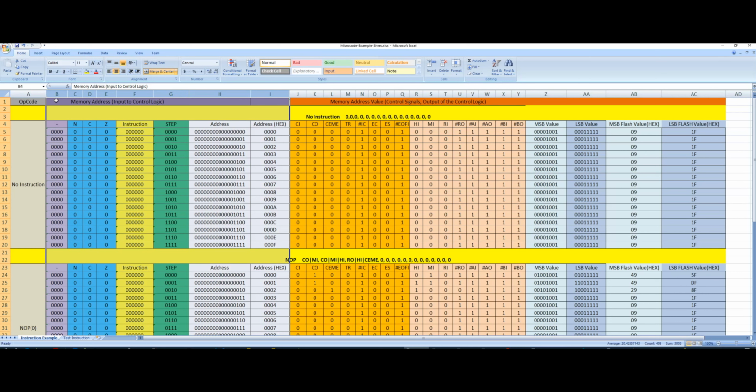If you look at it again, 4 bits plus another 3 bits for flags, another 6 bits for instruction, and finally we have 4 bits for steps. And if we put those bits all together, we're going to come up with an address, right? And that's the address that we're actually using to address the flash. And in this column, I'm just converting that binary value into hex. So this column is really the addresses that we will be writing to, right?